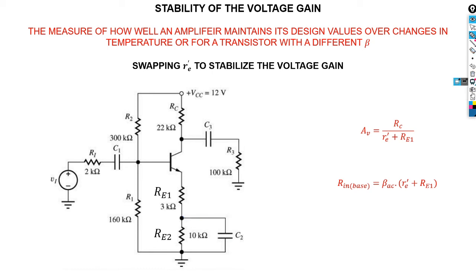So when you come here, if they give you such a question and you have to analyze, let's do our DC analysis. For our DC analysis, we come here from the source, and this circuit here will represent our DC circuit. This will be our DC circuit. So when doing the calculation to look for your emitter, this will be your DC circuit.